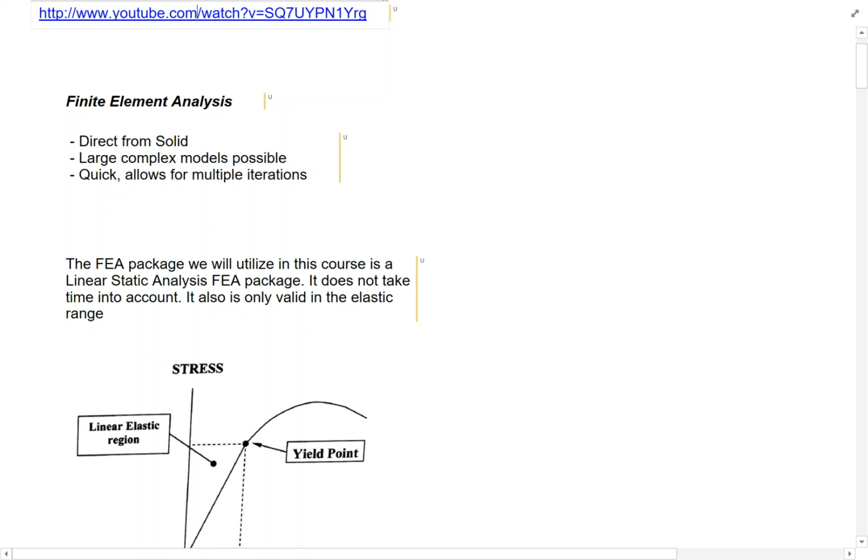I can model that thermal stress, and I can combine those stresses so I can determine the total stress on the structure, not only from the mechanical loading, but also from the thermal gradient that I've got on it. So it's a huge thing, and if solid modeling takes longer, the benefits that you get are just absolutely enormous. So that's my pitch. I don't sell solid modelers, but if I did, I'd probably be a pretty good salesman. But that's really the issue. That's where the real benefit comes from.